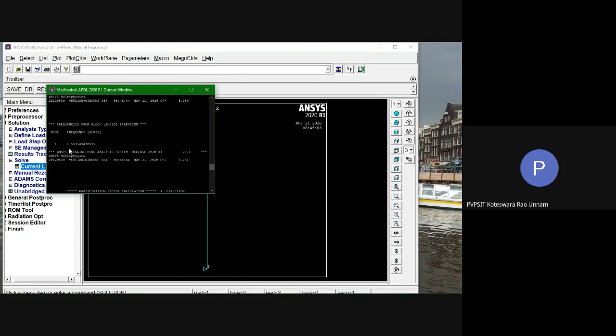Okay, so I think this is our value, 1.59. This matches with our analytical solution. So we need to do only up to this. We need to compare this value to that, and find out the percentage of error. If the error is less than 1% or 2%, your solution is accepted. Okay, so this is how you can solve the problem.